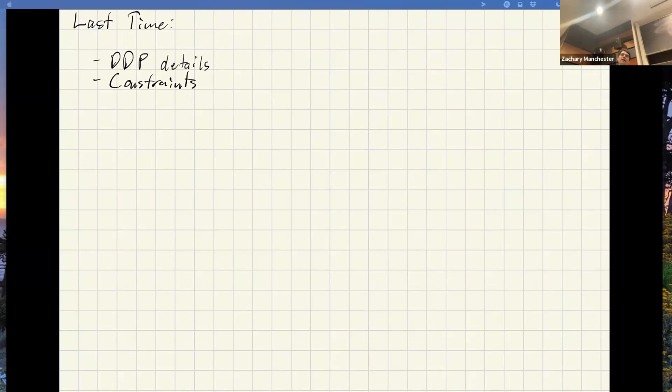Input constraints are okay. You can actually, like Pontryagin, put the input constraints on explicitly in the backward pass and solve little QPs. But state constraints are much harder. And classically, people use penalty methods or augmented Lagrangian methods, where they basically try to stuff some sort of constraint penalty into the cost function and then do iLQR on top of that. There are pros and cons for all these things.